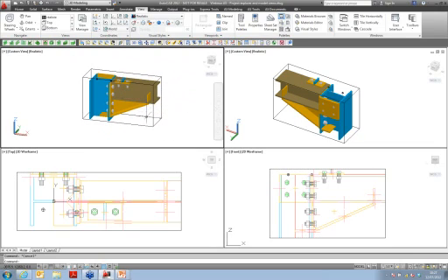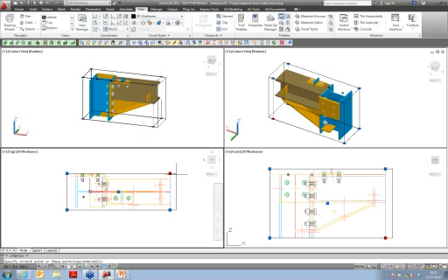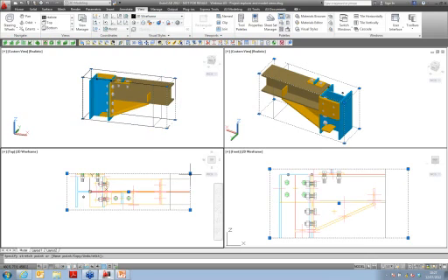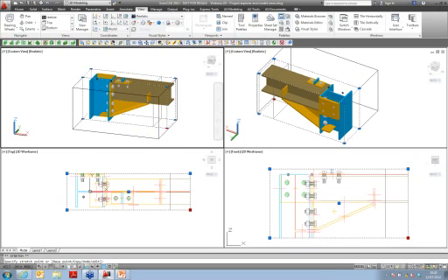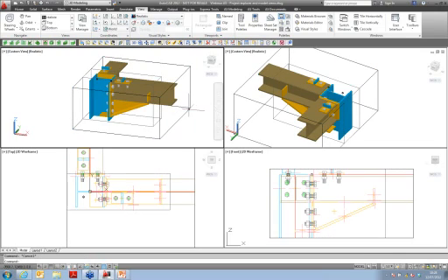What is also very nice is that you can stretch the box. You can take the model view, which is there. You have access to grips, and you can extend it as you want. You see, you can give a value or extend it on screen. You can also, in the 3D view, take this grip point and move it to this side or to the other side, and you get more display of your building.